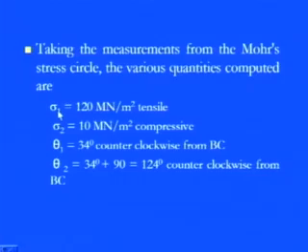So these values can easily be obtained, you don't have to calculate those things, what is the value of the sigma x, sigma y, tau xy, sigma theta, tau theta, all those things. Straight away plot sigma x, sigma y, tau xy, with the use of this information, plot the Mohr circle curve and get those values by measuring.